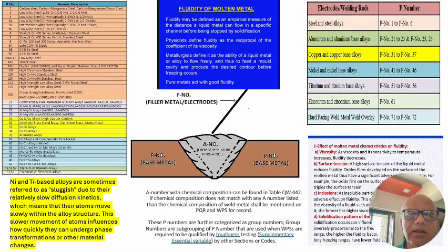I'm making a mistake. I think let's do it again. What I said is 0.2% carbon and 0.1% carbon. So 0.2% is going to be in the parent metal and 20% of the weld metal is going to be coming from the parent metal of 0.2. So 0.2 into 20% brings us 0.04.